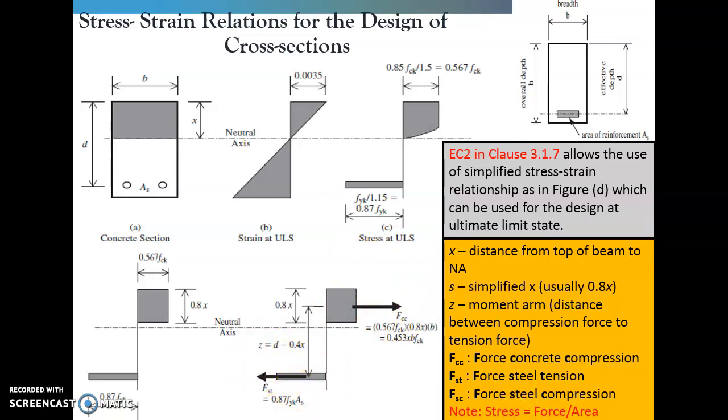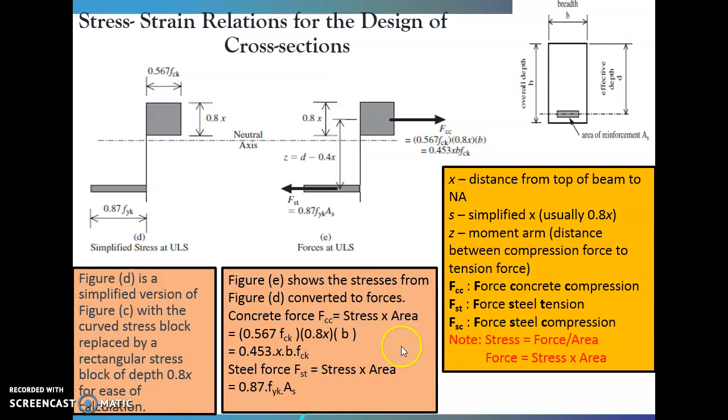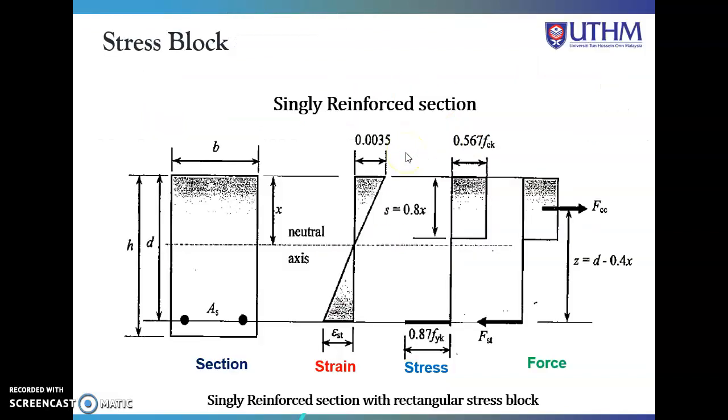Okay, so we note that force is the stress times the area. So we get this value for the forces. So figure d is the simplified one. We are using 0.8 as the depth for easy calculation, and this one is for calculating the forces. Okay, this is the stress block for the singly reinforced beam.